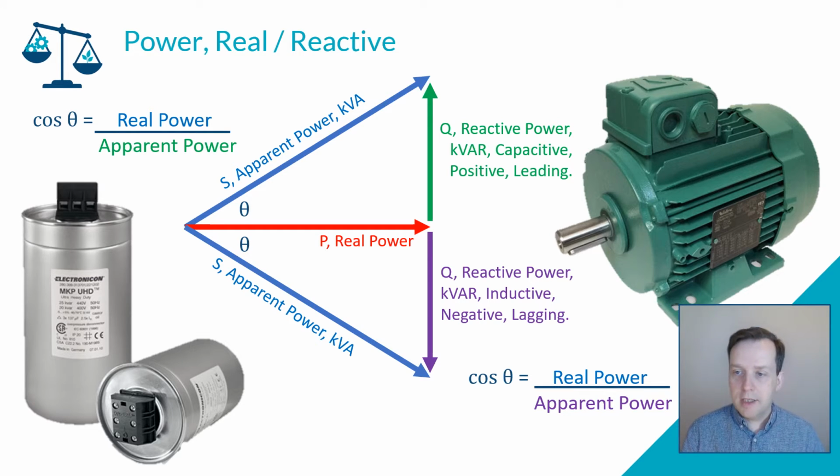So the more machines you have, like production lines, conveyor belts, electrical motors, compressors, you want to add capacitors in order to pull your apparent power closer back to this real power line. And there's a number of mechanisms, the reactive power compensation, where you have capacitors that connect into your power supply as more motors connect in.